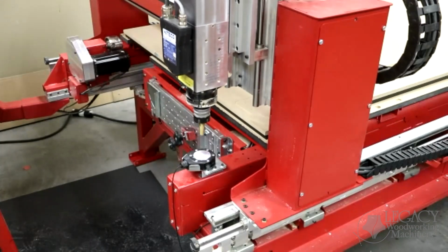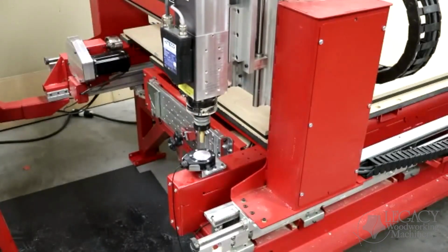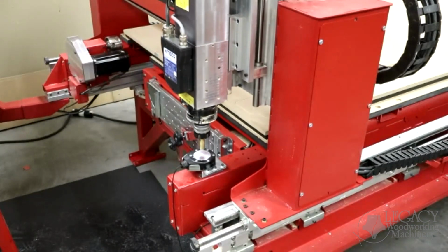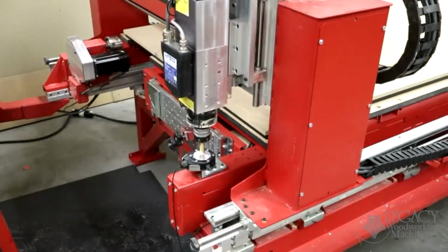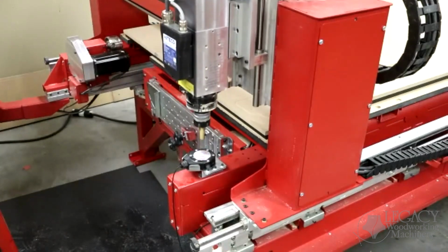So your longest tool will only have a 1/4 inch clearance. If you ever buy a longer tool, then you need to reset up your rapid Z for that new tool before you try to do a Smart Tool touch off. Otherwise, it would rapid probe right into there, crash before it starts to probe. Okay.